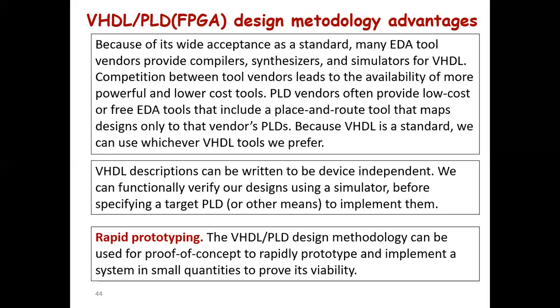PLD vendors often provide low cost or free EDA tools that include a place and route tool that maps designs only to that vendor's PLD. Because VHDL is a standard, we can use whichever VHDL tools we prefer. VHDL descriptions can be written to be device independent.